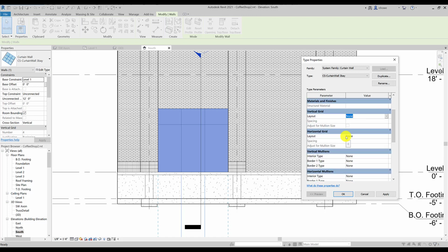But if, say, you had a 40-foot long by 40-foot tall curtain wall, you could tell it to be equal spaced, so many number of mullions, or panels. So you could say there's going to be 10 panels in that, or you could say every 5 feet stick one, or maximum of 5 feet, or you name it.